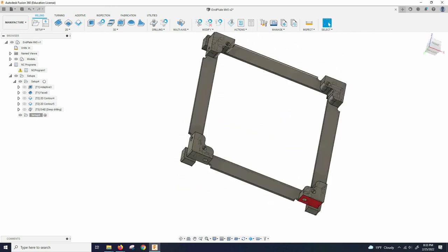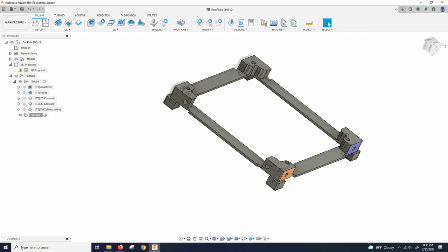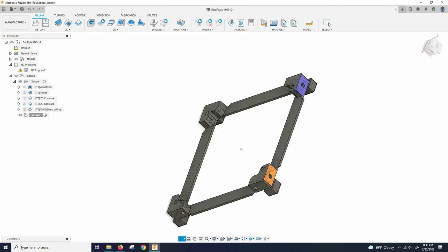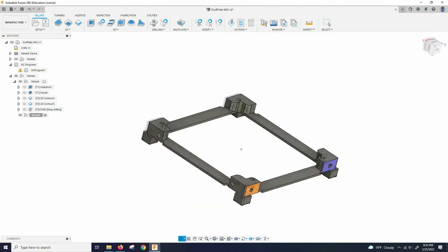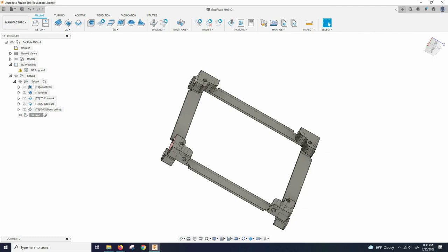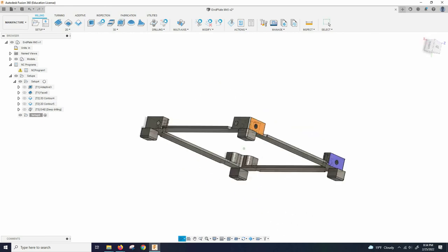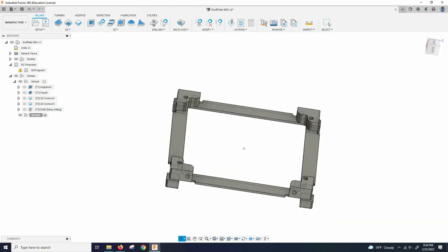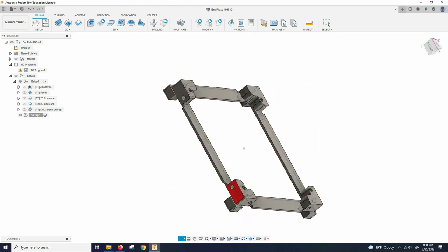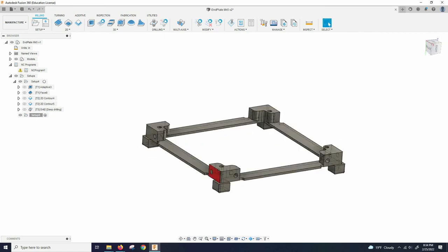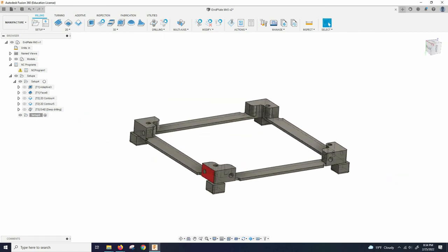And then the first one, I definitely recommend cutting it in something softer like plastic, so you can see how things work. And then you can cut all of them once you need it. Always plan to make more than you need. I know you need 2 of them, but you should plan to make 4 to 5 of them. I know it's a lot of material, but you're going to screw one up. I've screwed plenty of parts up. Unless you're a professional machinist who's been doing it for 20 or more years, you're not going to get it right on the first try.